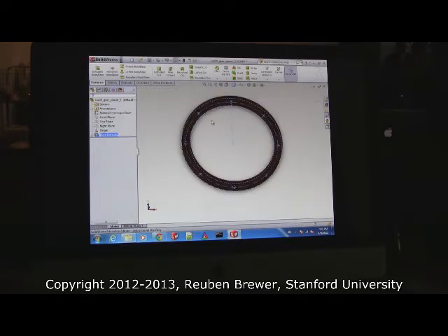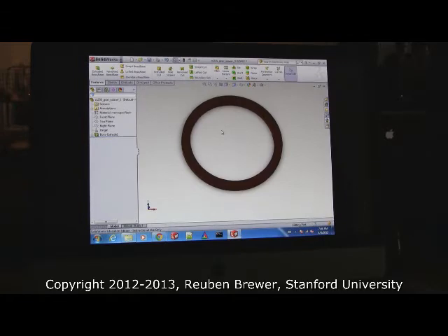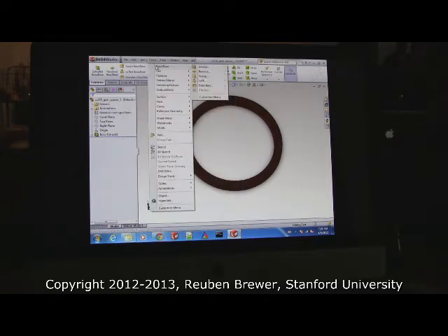Okay? Another button. If you don't have the button, go to SolidWorks, Insert, Boss. So everybody look at my screen for a sec. Again, SolidWorks configures very differently on different computers and you can change it. And so these buttons here are also all in little drop down icon things up here. SolidWorks, Insert, Boss, Extrude.